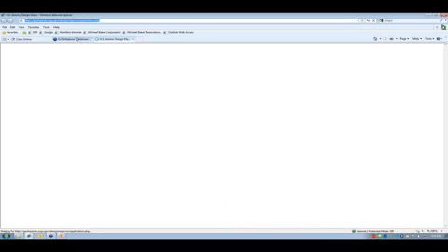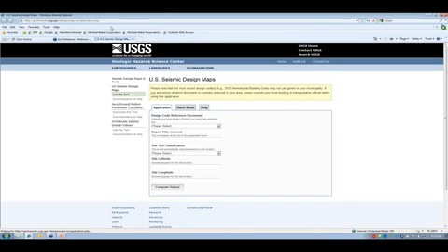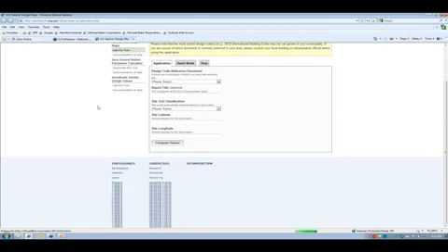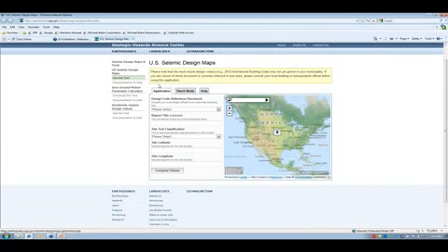Okay, if I go to this website, let's say this is a USGS website. Please select the code. I would say 2009 AASHTO as the hazard data, and then report type also test, and say site soil classifications. I say site class D, which is stiff soil.